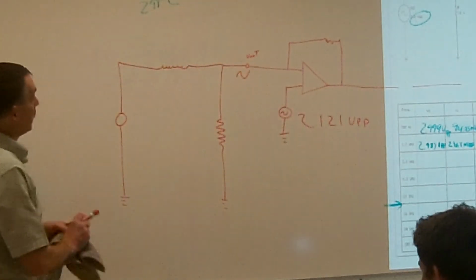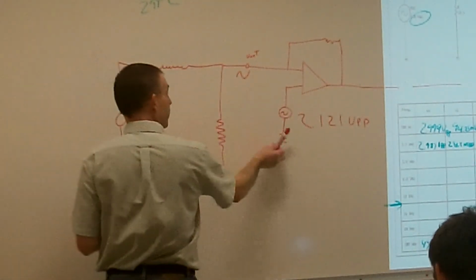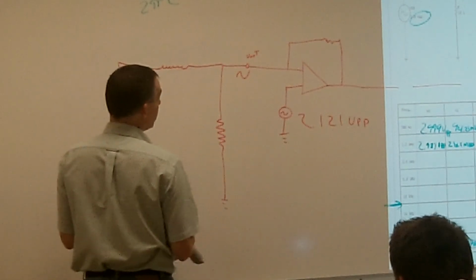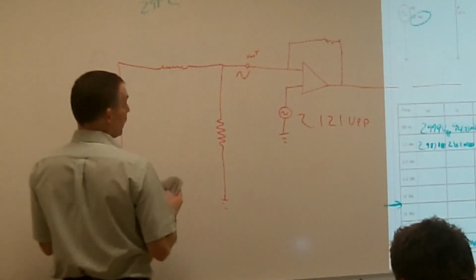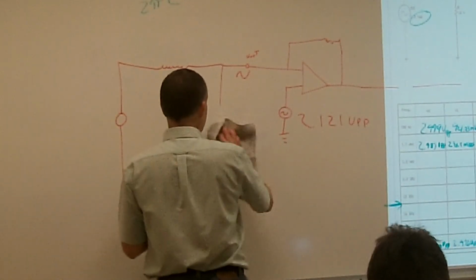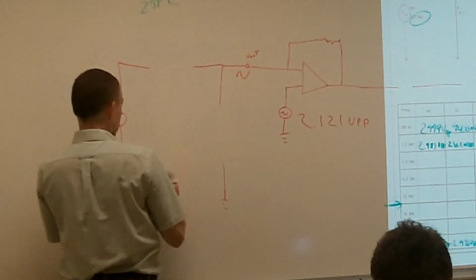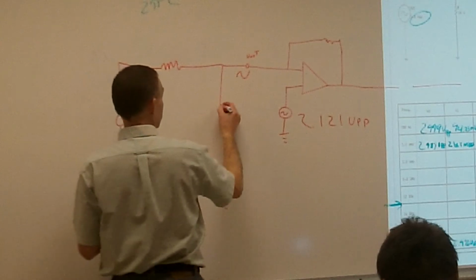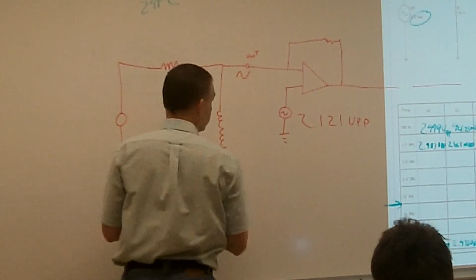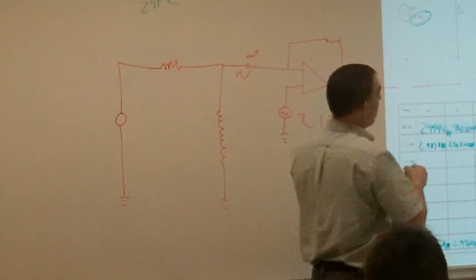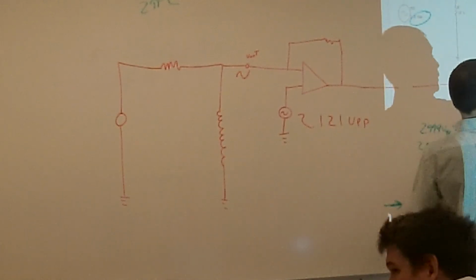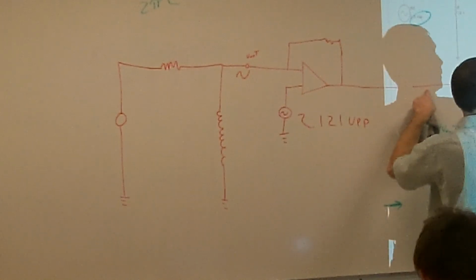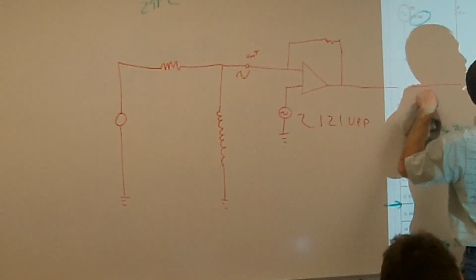So this one here gives me all my low frequencies, anything from 15.92 kilohertz and less. Then if I want to do the opposite, if I only want to filter out higher frequencies, then I just put my 2 components around. I put my resistor up here, and now I measure across my inductor. Now my inductor, as I start to go up, nothing's going to happen. It's going to reject all the signals up until it gets to the 15.92 kilohertz.